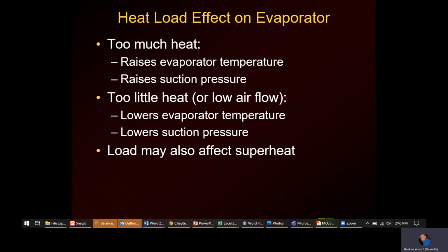All right, so high load, low load. If you've got a hot pull down, a room that's very, very hot, it's been down all day, you get it fixed, and it's 85 degrees in the house, you're still going to follow your TD more than a desired supply temperature.